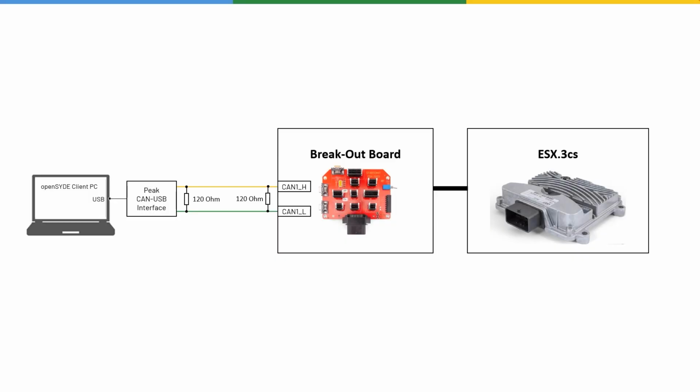If you are not sure which bitrate the CAN bus of a controller is set to, for example, because the controller has not been delivered fresh from STW but perhaps comes from a test setup whose configuration you do not know, you have to try the bitrates one after the other. In parallel, you can use the tools of OpenSide and PEAK and observe the CAN bus. In our test setup, we have now included a controller with an unknown bitrate.